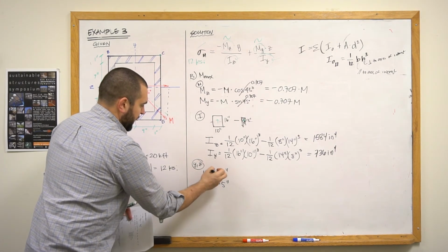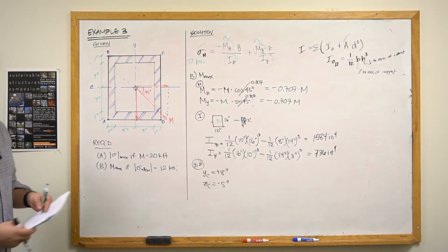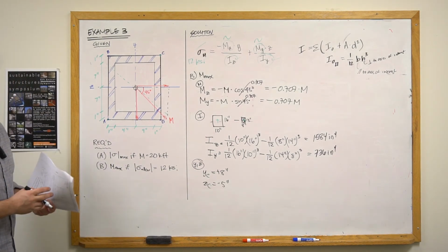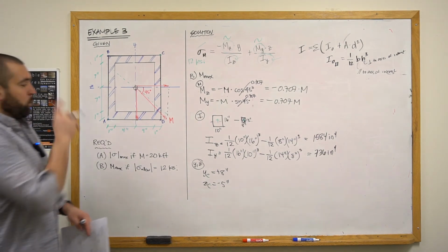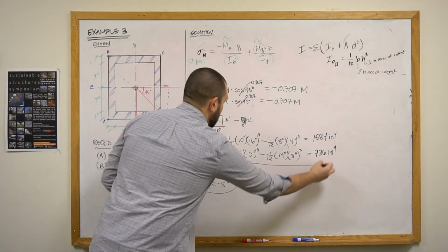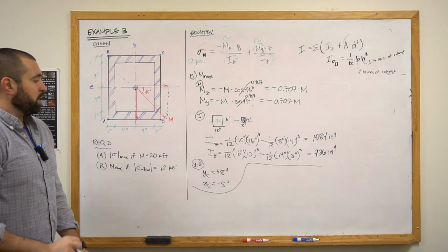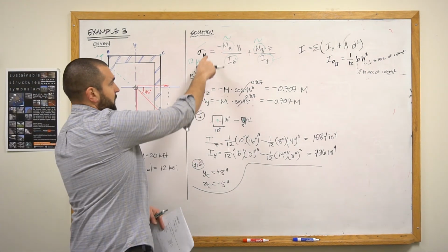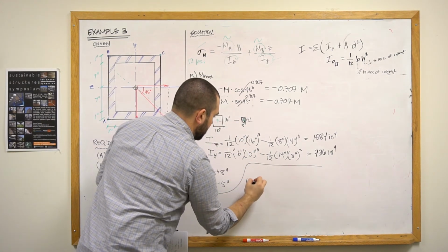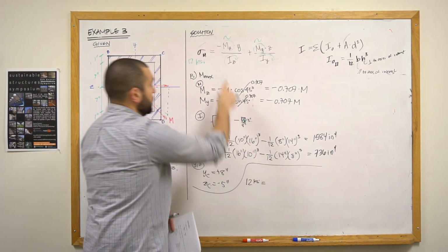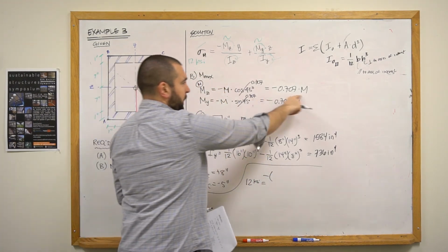So the only difference is that we switch the signs on each of these. Now we're going to get a positive stress, but even if we got a negative, all we cared about was the magnitude anyway. Okay, so we're going to use this equation again, but we're going to need to rearrange it a little bit once we've plugged in our values, because the maximum normal stress we know is 12 ksi, and that's equal to minus Mz. Mz is now variable.